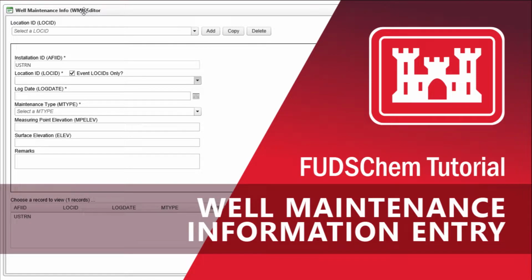This video will go over how to enter well maintenance information into FUDSChem. Well maintenance information can be entered anytime a maintenance activity is performed on a well. Maintenance activities range from painting the well to repairing the well. Abandoning a well, or changes to well casing or ground surface elevations can also be captured here.